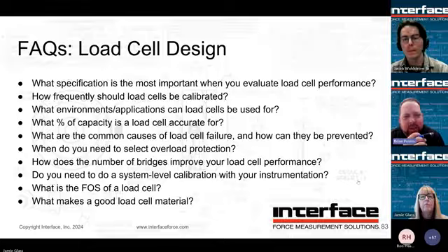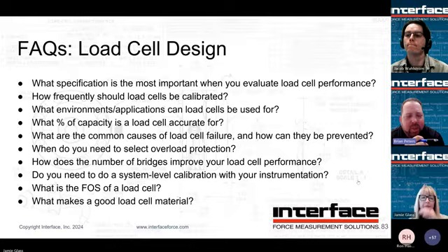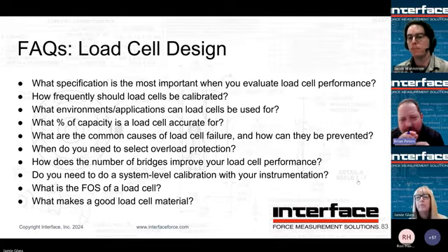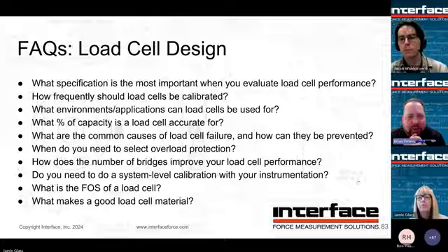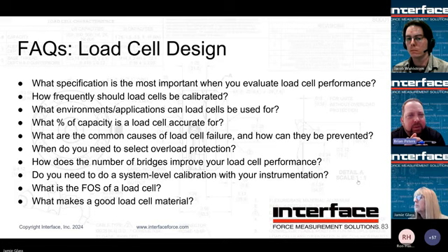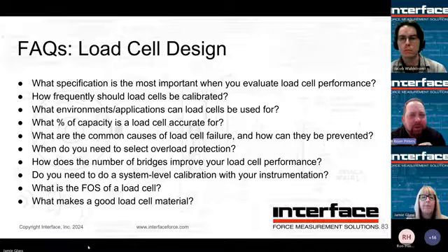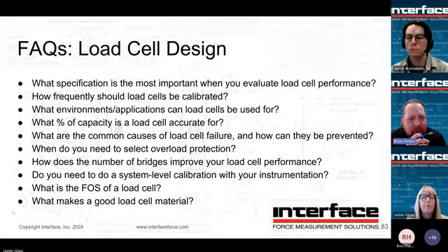Yeah, and we typically recommend tighter intervals as the load cells are newer. They get better with age and more stable with age. I'm talking very, very small amounts. So typically customers would recal at least on an annual basis until they have good confidence in repeated cals to say that they can be extended. We've done that. Some of our standards, for example, we're able to extend them out a couple of years.